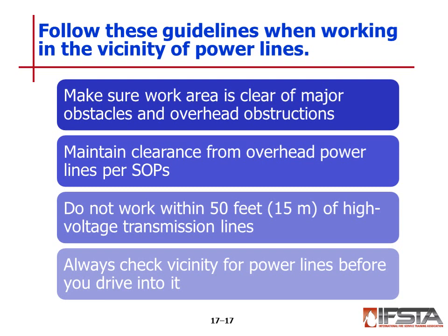High tension wires transport electricity over long distances. They are higher voltage than lower voltage lines, but will still be within reach of the aerial platform or aerial device. Interview representatives in your area and learn to recognize the differences. Look up and live. Always check the operating vicinity for power lines before you drive into it.